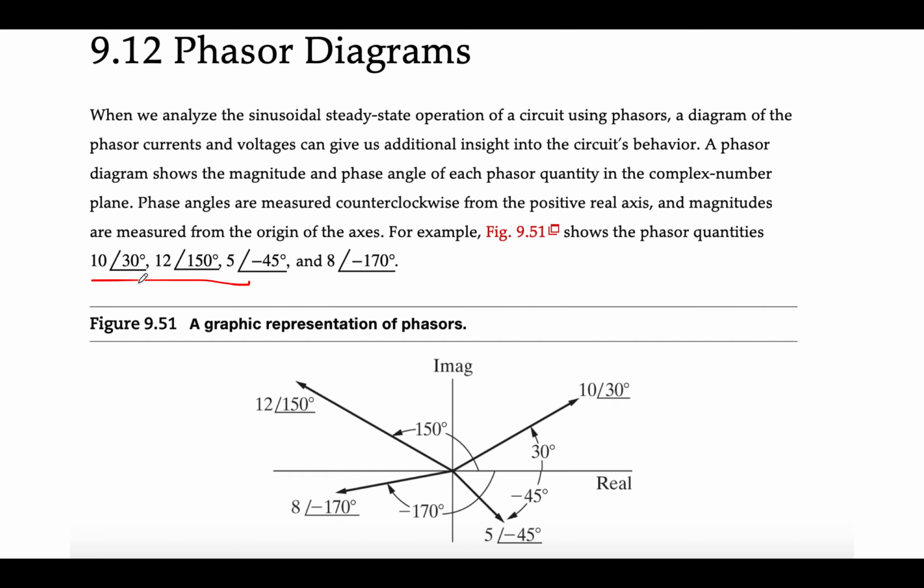In a phasor diagram, as in the kinds of complex plane representations that you will use from here on in electrical engineering, we use the complex plane where the vertical axis is the imaginary axis and the horizontal axis is the real axis. If this were given in rectangular form, the real part of the complex number would be marked off on the real axis, the imaginary part on the imaginary axis, like a line to a point with two components. The only difference here is that instead of rectangular components x and y, we have phasor components, real and imaginary.